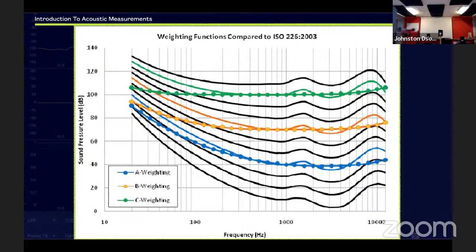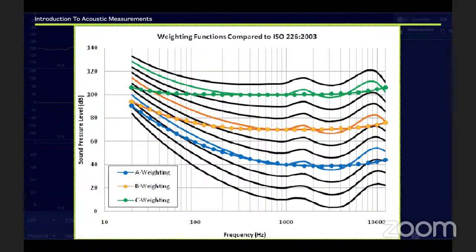I'm going to play some noise on the speakers, and I'm going to show you this SPL meter that's in my hand. I'm going to do an A weighted reading and a C weighted reading and we'll see how it is different. You will notice that the C weighted gets a little more louder, in the sense that the reading gets higher, not the speakers. The speakers are not going to get louder. They're going to remain at the level they are playing. Only the reading will get maybe a couple of dB higher compared to the A weighted scale, because C weighted takes in more information in the low frequencies. Okay?